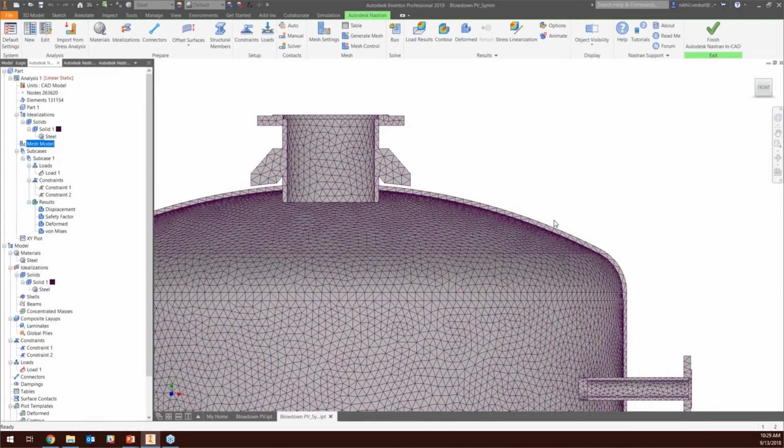What I like to do, when I first start doing some simulations, some design validation of my particular design, is go with a more coarse element size to start out with, and just run your analysis. And if you see what's expected, like I'm applying a load here, if there's a deformation in that area, sure, that's expected.